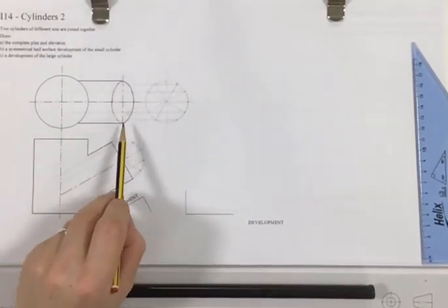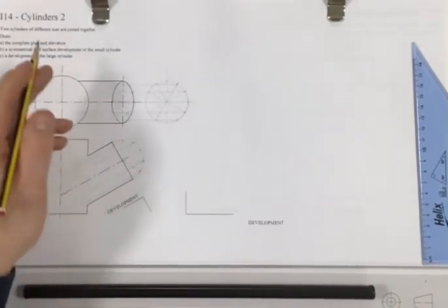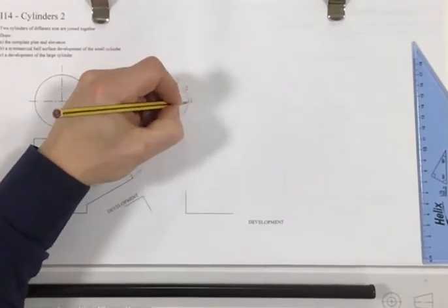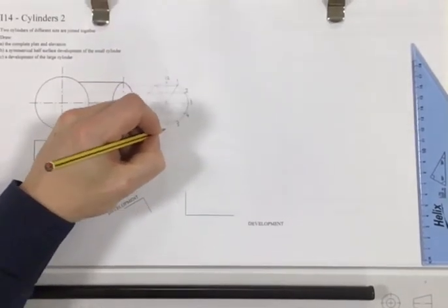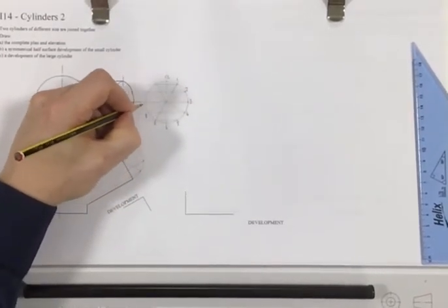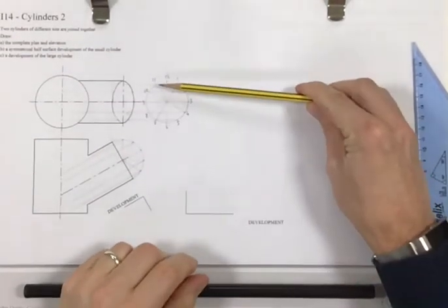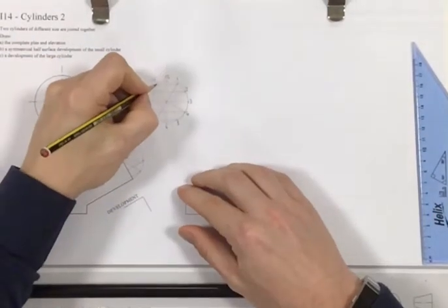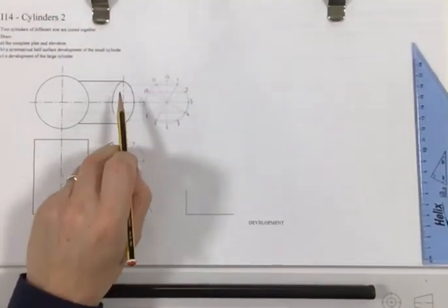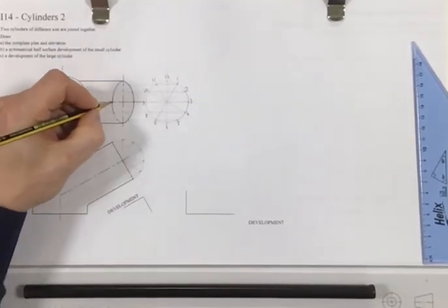Now at this point, you notice there that I used 12 segments. It's wise to use the numbering from a clock face at this point, starting at 12 in the same position as the clock, and knowing that each of these points therefore refers to a point on this. So for example, that's 12 o'clock, that's 6 o'clock, that's 3 o'clock, and that's 9 o'clock, and so on and so forth.